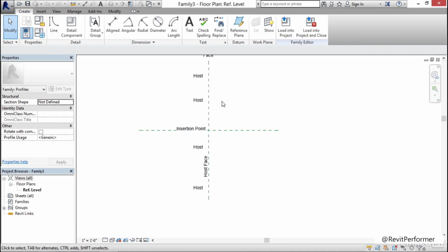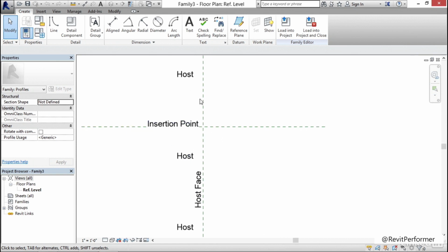These are the most important part of a Revit family. These are what drive the model. I like to consider them the skeleton of the model. First and foremost, we add reference planes, we dimension them, and then we put our 3D extrusions or our line work on top of the reference planes so everything is flexible.